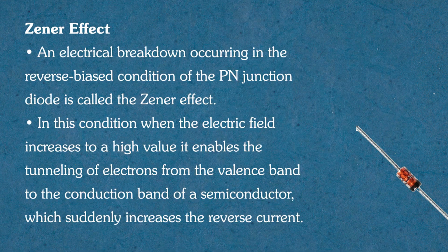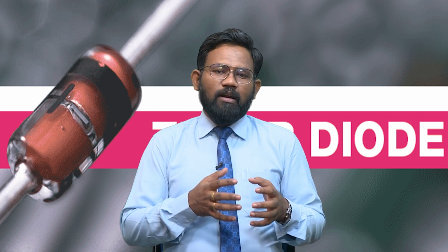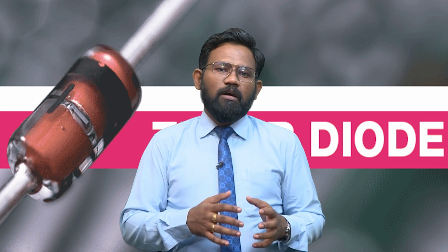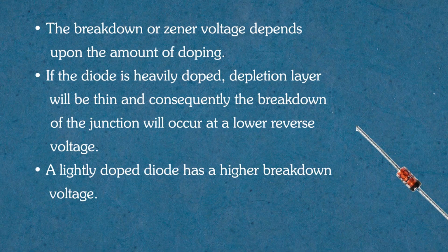So in this condition, when the electric field increases to a high value, it enables the tunneling of electrons from the valence band to the conduction band of a semiconductor, which suddenly increases the reverse current. So the Zener effect is nothing but the principle of working for the Zener diode. In this, what happens is that when the electric field increases to a high value, it allows the electrons to flow from the valence band to the conduction band, and in this way the conduction of current takes place in Zener diode. The breakdown or Zener voltage depends upon the amount of doping.